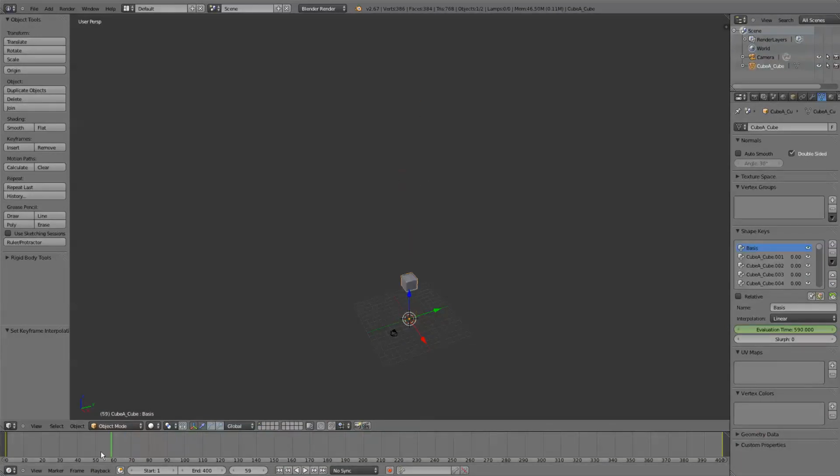But unlike having it controlled by Blender's cloth simulation, we can move it, rotate it, scale it, duplicate it, add modifiers to it, perform any operation that we can apply to any normal Blender object. If we were to render it using Blender Internal with motion blur, everything would work correctly. One additional step we can do at this stage is to put the origin of the object in a more useful position, which for our needs would be in the center of the object when it's in its final position.